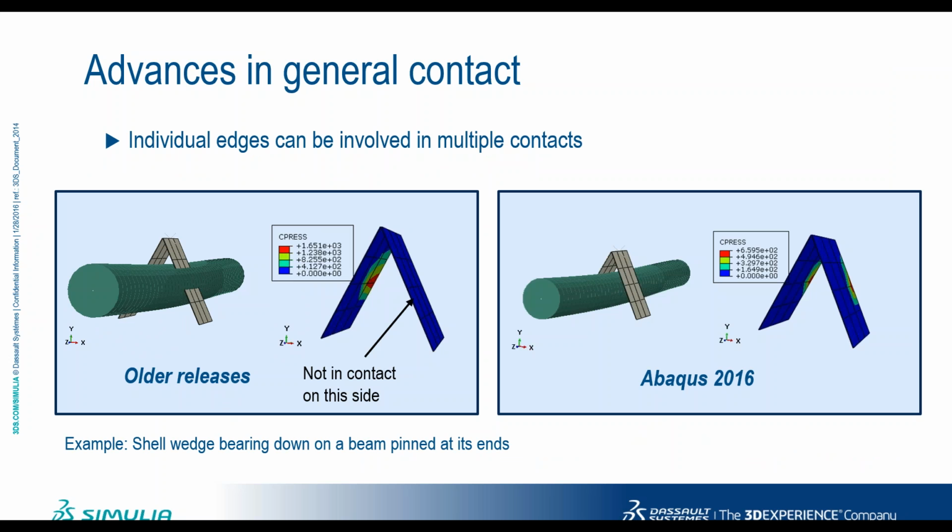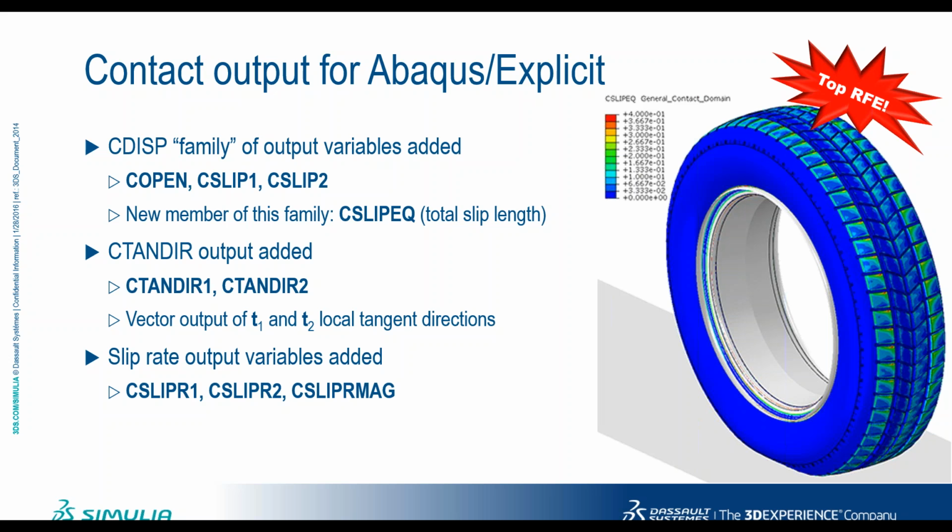Also, edges. You can define edges in contact similarly to the points. You can see the difference in these pictures. There's a significant difference in terms of contact pressures and in terms of simulation accuracy.